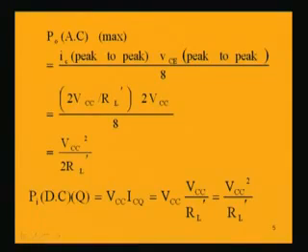We are finding the average power, and the average AC power is given by IC peak to peak into VCE peak to peak by 8, which we found earlier in the class A series fed power amplifier, and we have deduced that. So, putting down the values of IC peak to peak and VCE peak to peak.